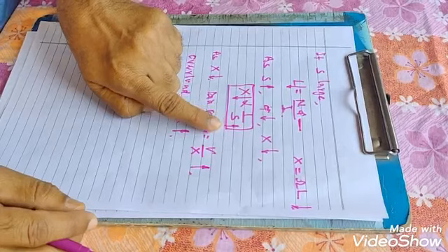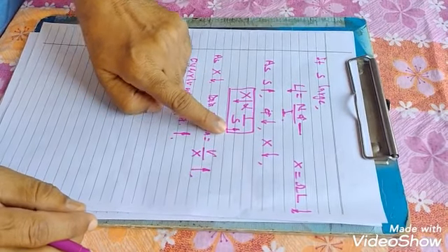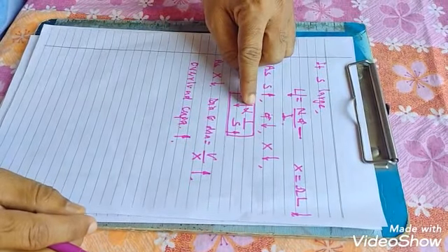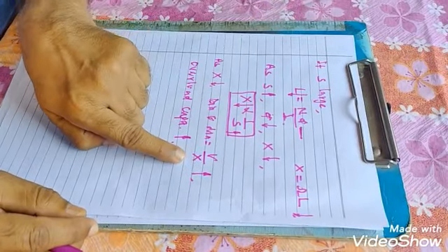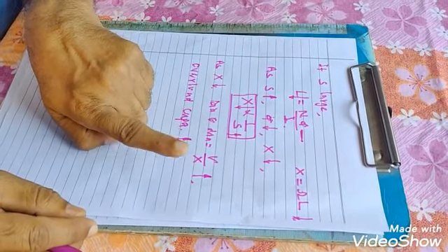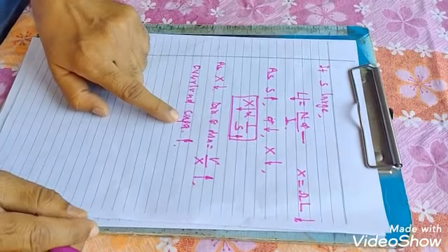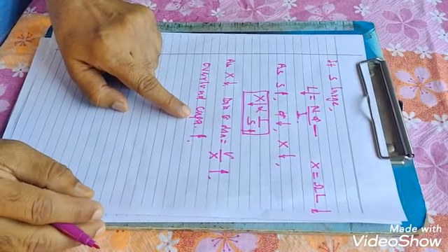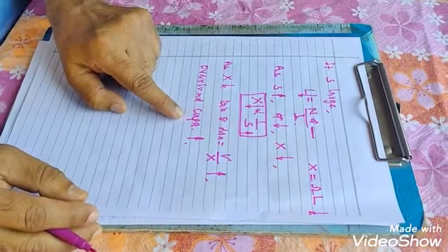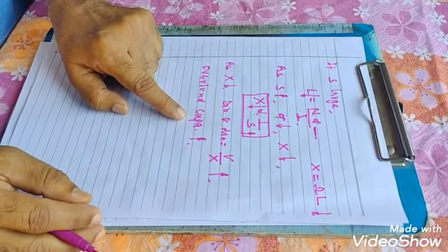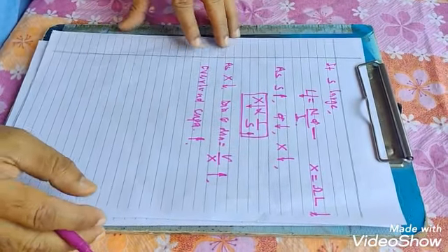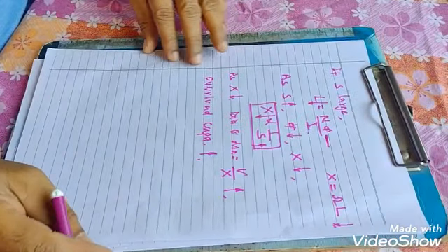So if we select a large number of slots, leakage reactance is less. Therefore, the diameter of the circle diagram is increasing, and therefore overload capacity is increasing.